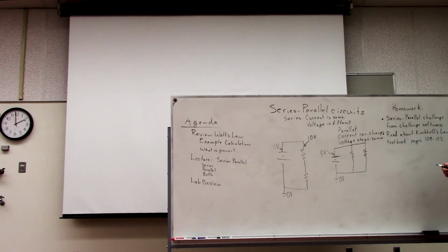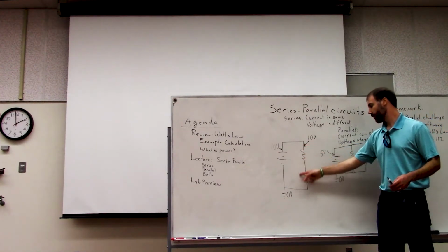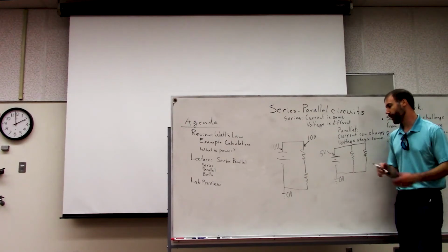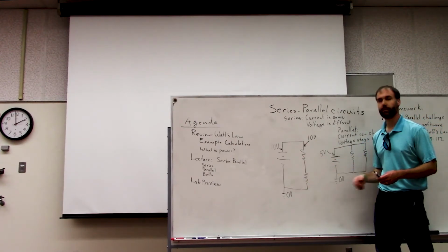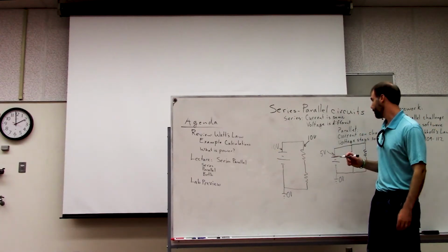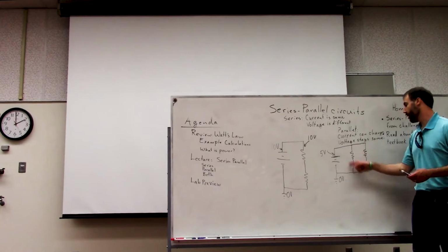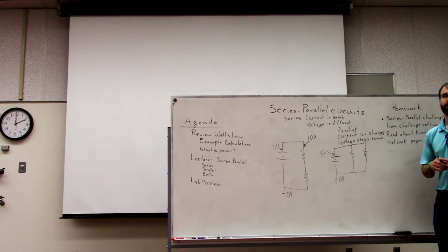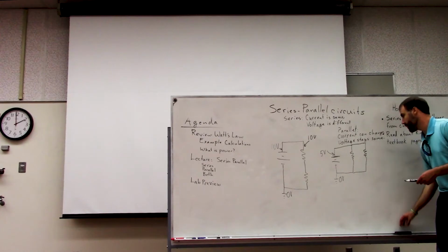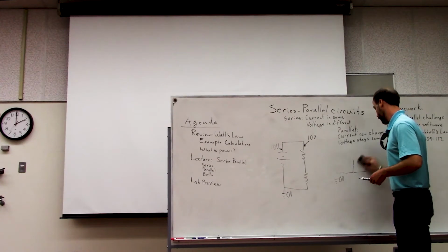So with both series and parallel circuits, we were able to redraw the circuits as simpler versions, right? We could find equivalent resistors and redraw the circuits, right? So how did we find an equivalent resistor for a series circuit? What formula did we use? Yeah, we just added them up. So that was fairly easy. What about with a parallel circuit? Yeah, we use this other one, 1 over R total equals 1 over R1 plus 1 over R2.